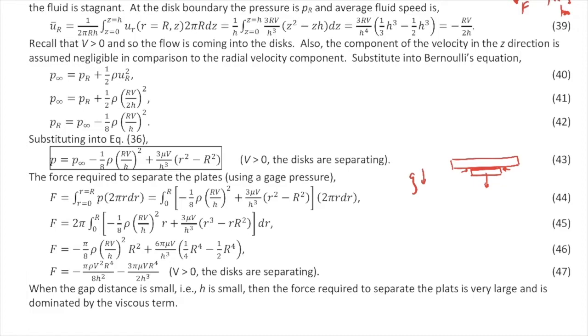This is a classic kind of lubrication problem. Lubrication problems in fluid mechanics appear when you deal with very small gap heights. And you can make these kind of scaling arguments that I did in this analysis. But I wanted you to see that here's something that we see in the real world: the mirror sticking to the surface of another mirror, and not falling right away. Why does that occur? How would you actually model it? And that's exactly what we did here to do the analysis.